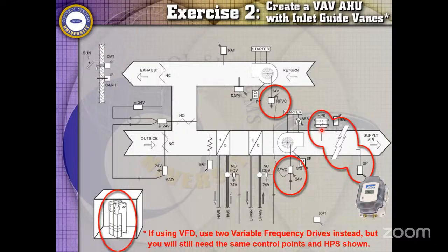The concern back in the day was that VFDs were not reliable because they weren't, and the guide vanes often broke with the dampers, the little guides in different spots. So the control of capacity for airflow sucked. So what they did is they put a high pressure switch in there, and if for any reason the VFD just ramped all the way up and its control broke and it was a piece of crap and whatever, we just kill power to everything and shut it all down. That's no longer needed. VFDs are much more reliable now. I have never seen a VFD since I started in 1997 just run away and keep running and never turn off. So not a big issue anymore. I never used one.